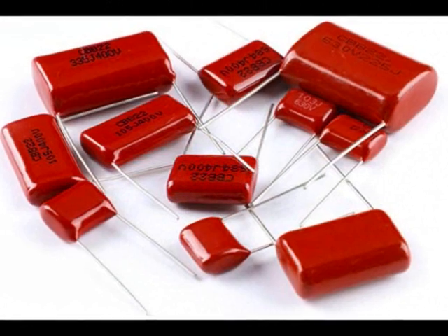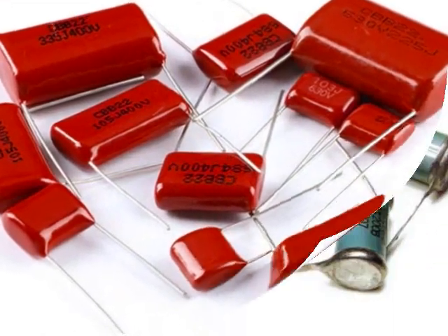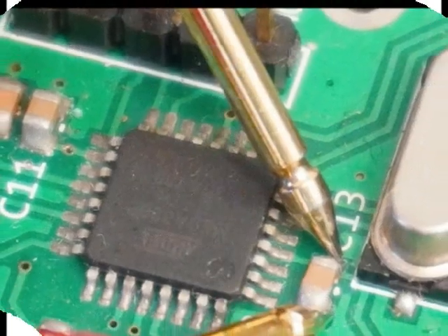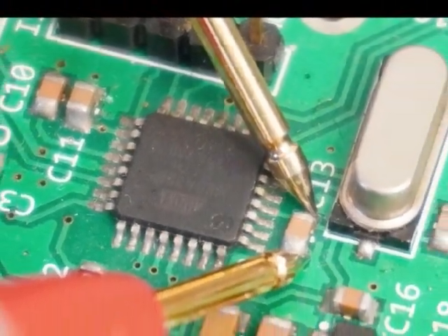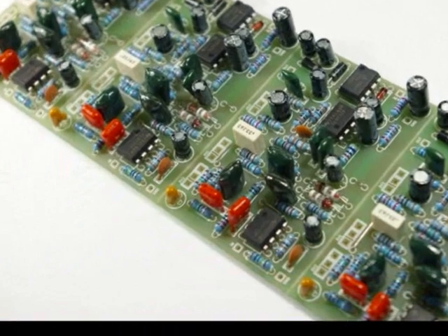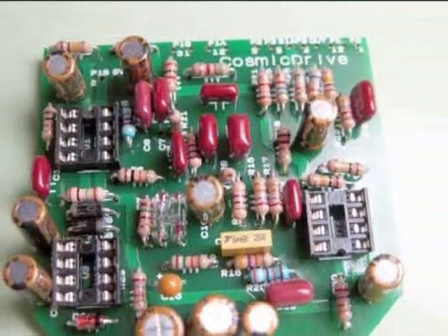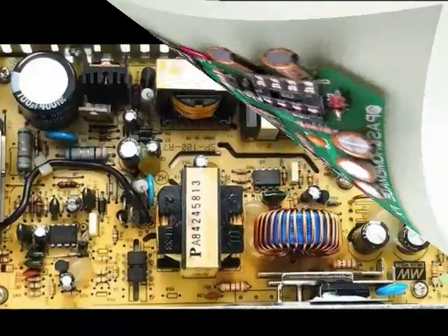One of the important applications of ceramic capacitors is to eliminate noise in the power supply of circuits. On the other hand, due to the excessive sensitivity of digital circuits to power supply voltage fluctuations, this type of capacitor is placed at the closest point to the IC in order to improve the power supply.